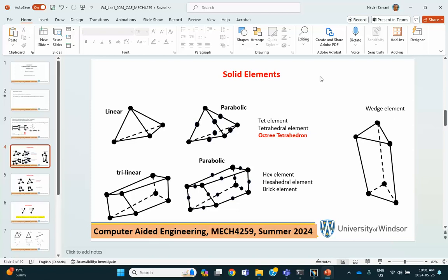In order to get a fancy mesh like that, these hex elements, you have to go to the advanced meshing tool. A collapsed version, if you take this one on the left and you collapse these nodes 1, 2, 3, what you get is a wedge element. So essentially, a wedge element is a modified version of the one on the left, and of course you get something that looks like a wedge. Okay, let's move on.